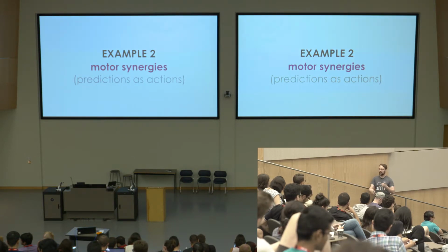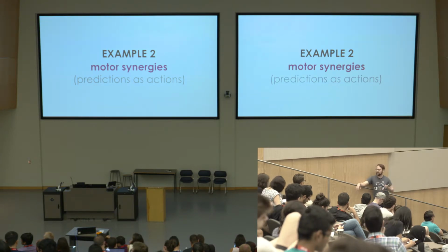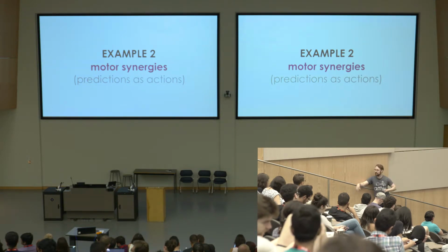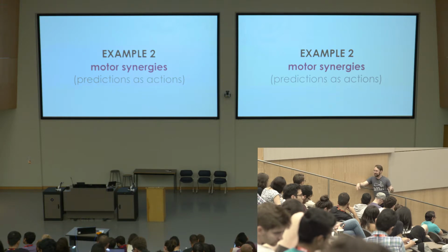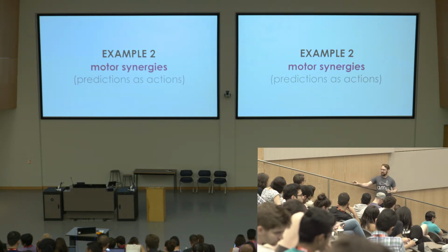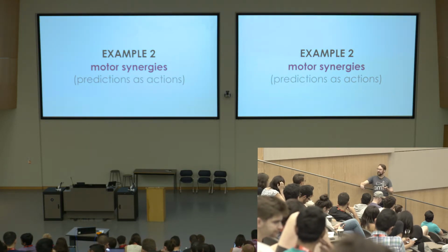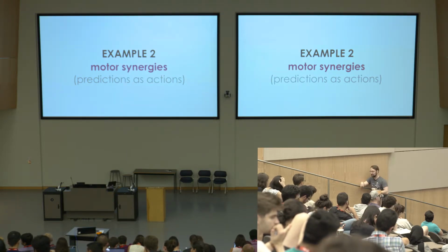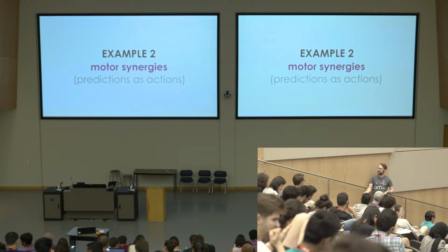So it can start to build up the prediction watching how a person switches between the different modes and functions. And then when the system begins to switch for the person, after it reaches, say, a certain threshold, that's the really simplified thing that we did, if it were to switch for the person and they were to switch back to something else, then its answer to the question, would the person use the thing I switched to, would be, no, they wouldn't. And so it'll decrease the prediction. So it's Pavlovian control in the sense that there's a hardwired mapping from the prediction to, in this case, the switching behavior of the system. And just by the user's activity, it will increase or decrease those predictions.